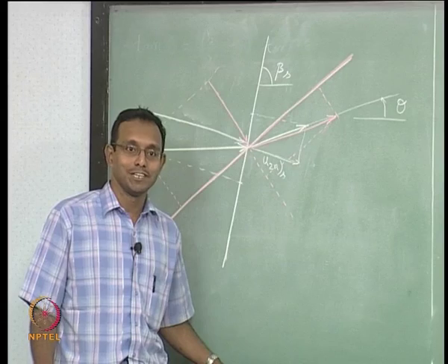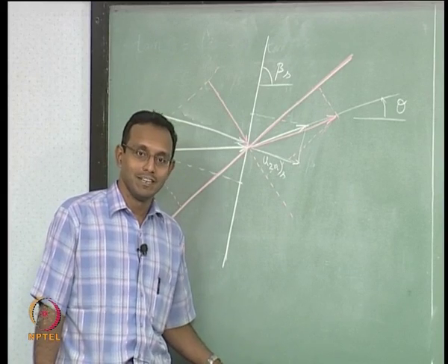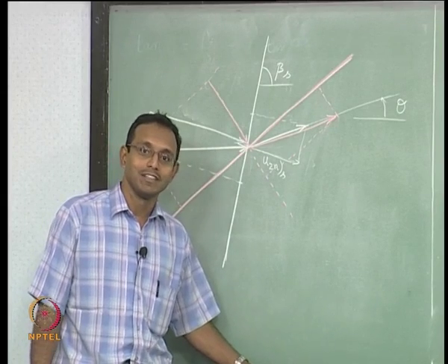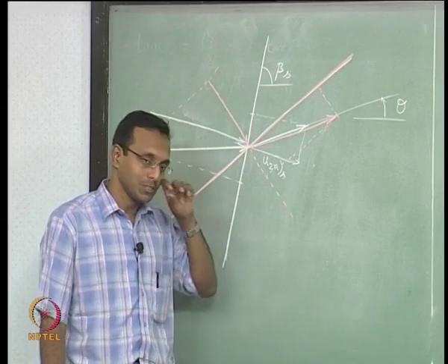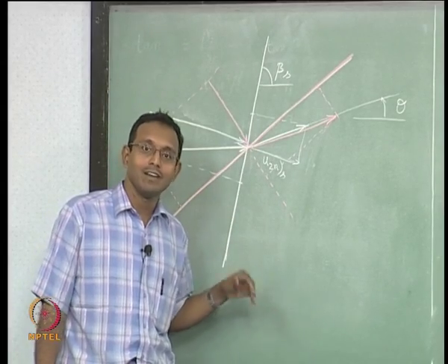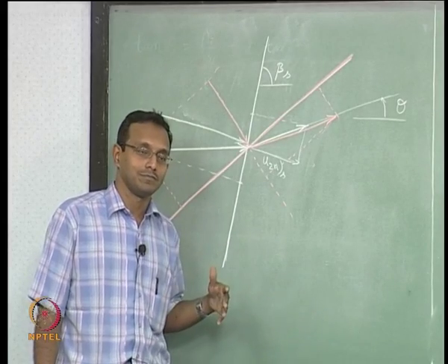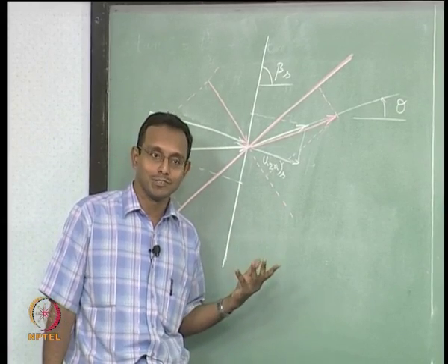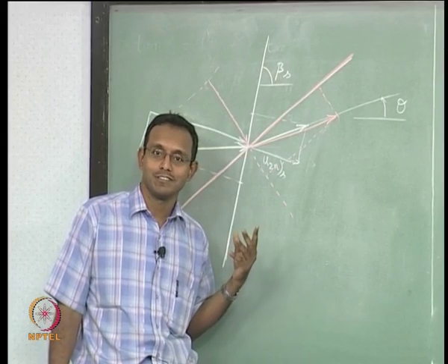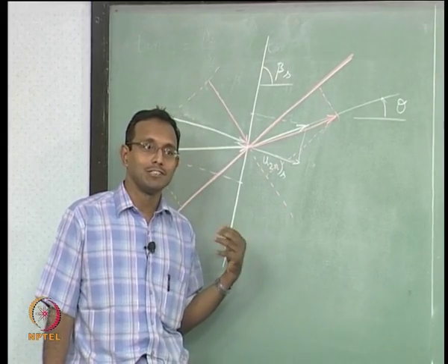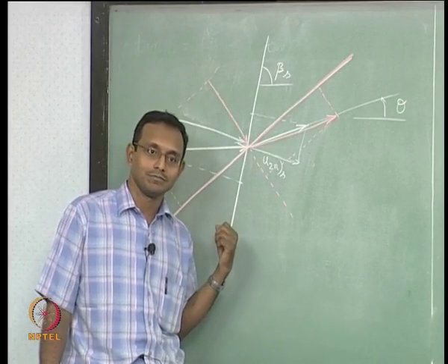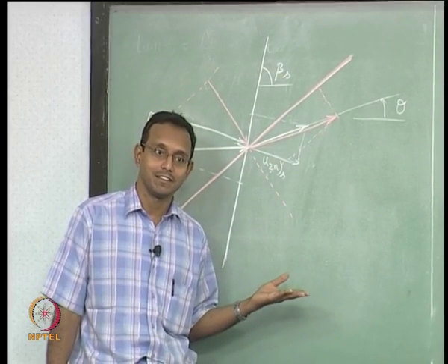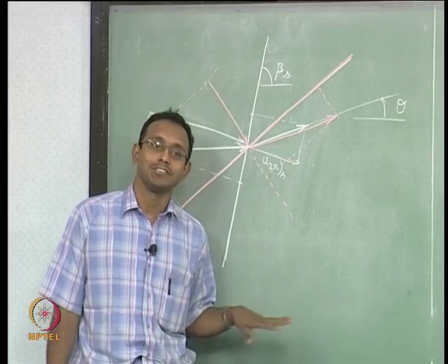That is the idea of stability here. It so happens that it has now been recently proved, recently in the sense it is last year or this year, that the strong shock solution is an unstable solution, while the weak shock solution is a stable solution. Because of that, if there is ever a formation of a strong shock solution, any small disturbance, noise, any small disturbance in the flow will throw it to a weak shock solution. That is why when we wait for long enough to form steady stable solution, steady state, and we are looking at the problem, we will always see only weak solutions.